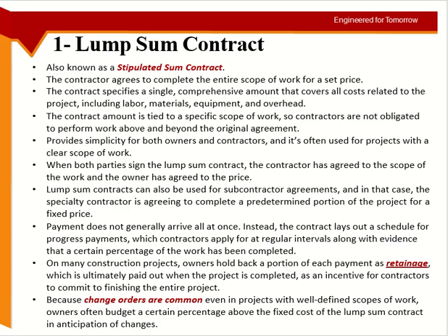So this type of contract sets up progress payments. When you complete this much amount of the work, I will give you 20%, 30%, and normally there is an advance amount as well. You start the work, we call it the startup amount or something like this. It can be given at regular intervals. So if the total project is 6 months, I'll give you 15-20% after every 2 months. Or it can be done according to the percentage of work done. In both cases, the contractor will provide some evidence that I have completed this much work.